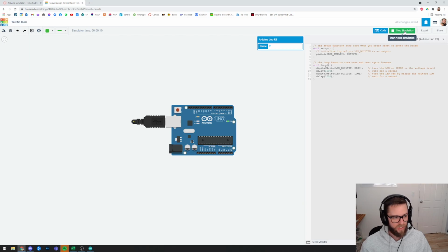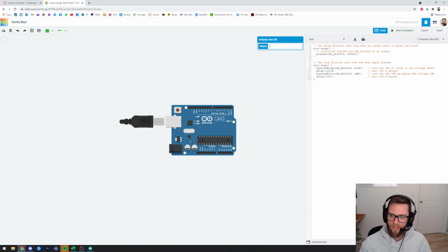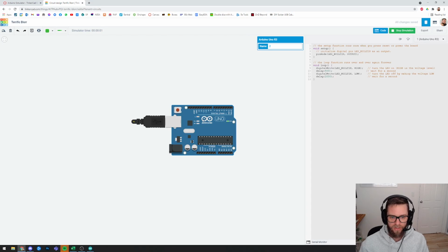Now what you can do, and this is what I encourage you to do with this code, and the purpose here is, don't just paste it and get it to work, but get your head around how this works. So we could change this to, maybe I want it to only be on for half a second, and then I want it to delay for 2 seconds. So you could change these parameters within the code and test it. So now it's going to turn on for half a second, delay for quite some time, and so on.